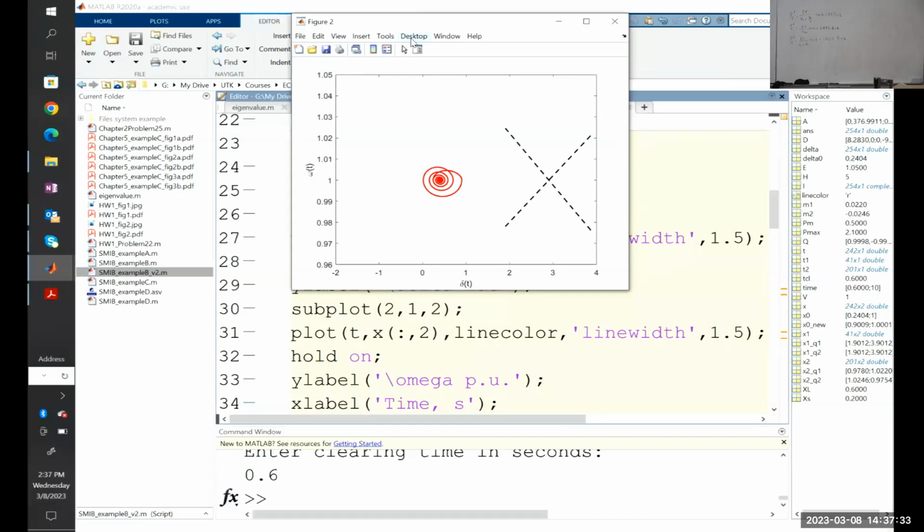So we have more demand because population grows and customers acquire new appliances, the demand starts increasing, generation starts increasing, but the transmission remains almost the same with minimal changes. With that, the system started becoming closer and closer to its limits and diminishing the stability margin. Yeah, and that has to do with this concept. If we have a better, stronger grid, then the system will have a larger margin for stability.